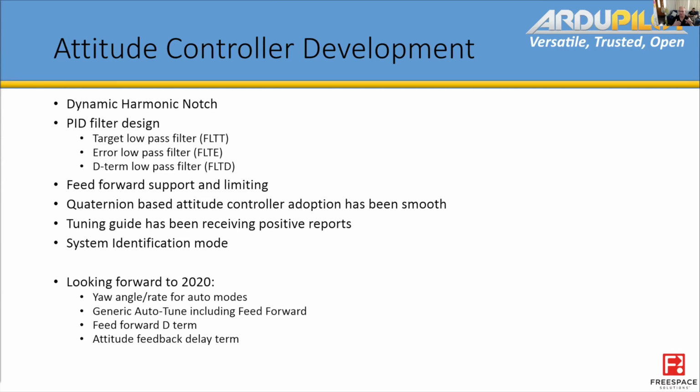This allows us to take care of a couple of other noise sources, including the raw noise coming in through the EKF gyro bias updates, which brings some step inputs through, and also the RC input, which is happening at a lower rate. So we actually see these steps in change of attitude, especially if you're moving slowly.